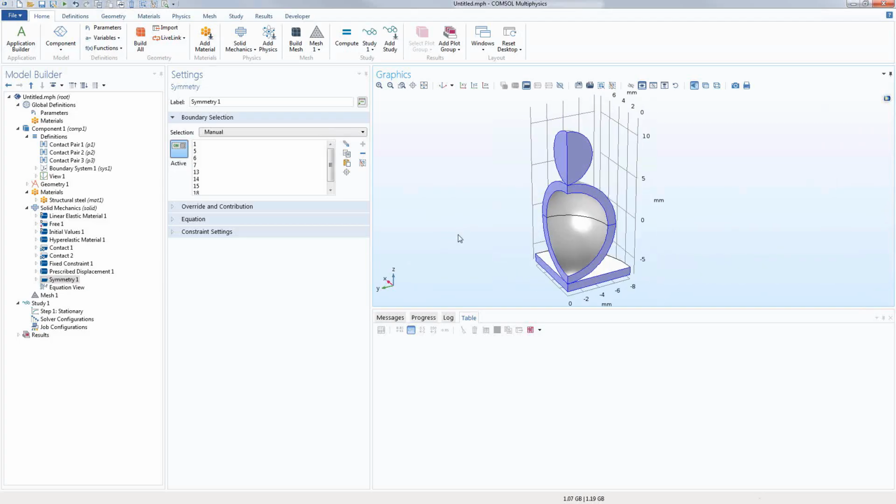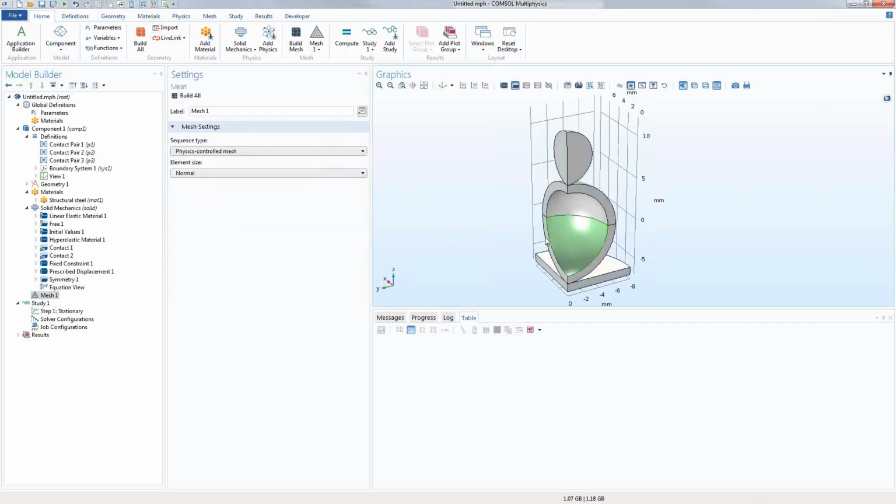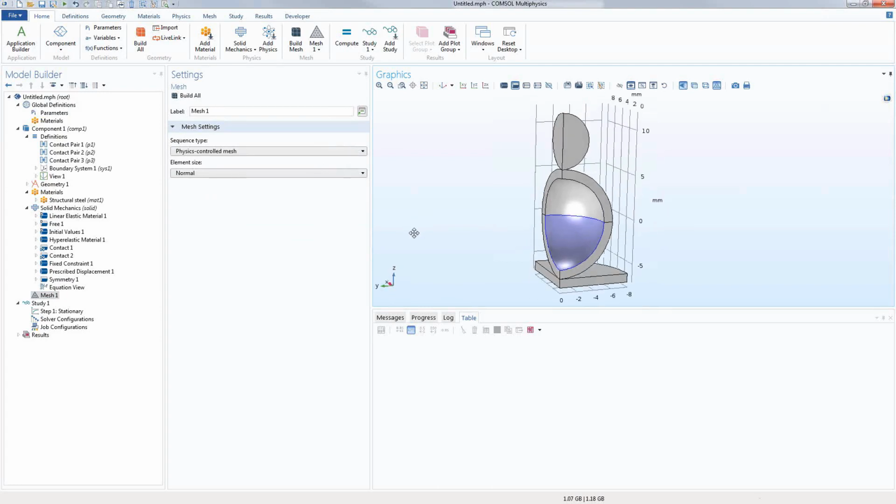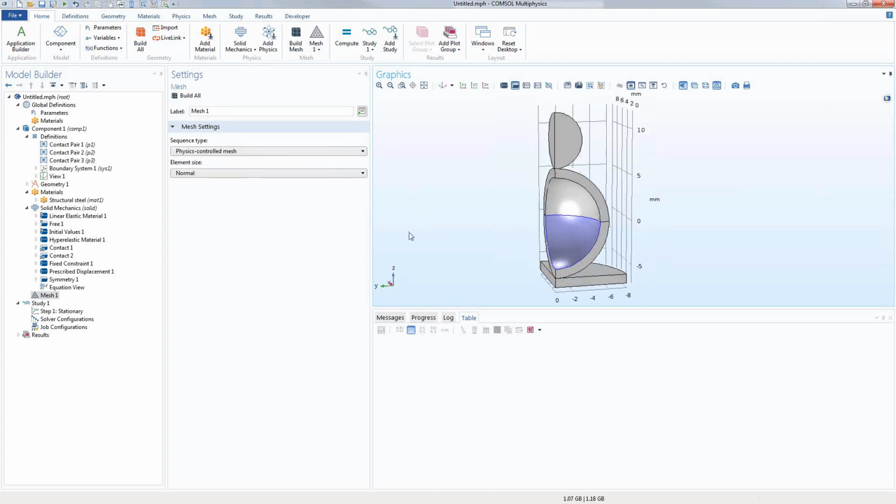Now what about the mesh? Now this is a very important criteria here, the meshing. You could go with the default tetrahedral mesh here, but that's not the one you would ideally want if you're going to compress something too much. So if you're going to compress something too much, you better have an isotropic mesh, which is usually created by using structured mesh. So in this case, to create a structured mesh, or let's say brick type elements or hexahedral